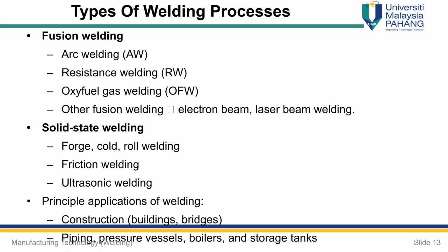Fusion welding processes include arc, resistance, oxy-fuel gas, electron beam, and laser beam welding. Solid-state welding includes forge, cold, roll, friction, and ultrasonic welding. Applications of welding are found in construction, piping, shipbuilding, and aerospace industries.